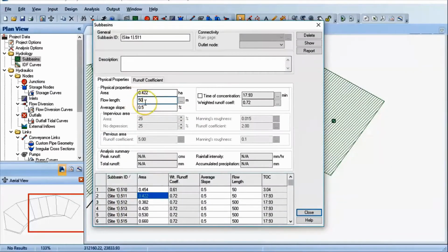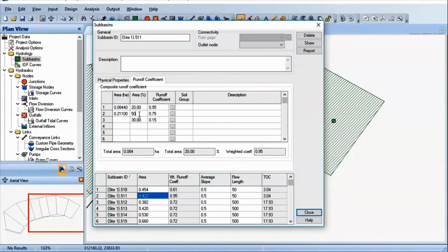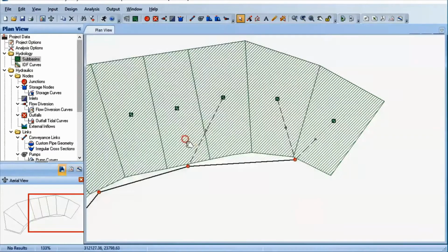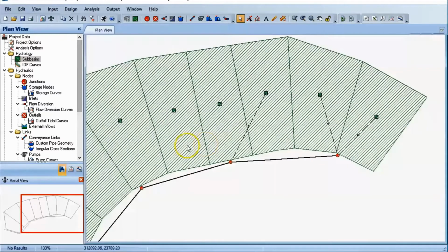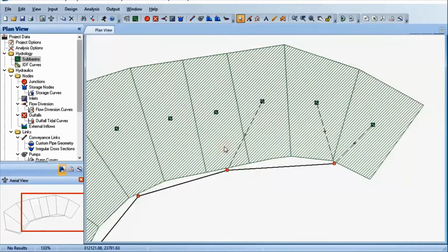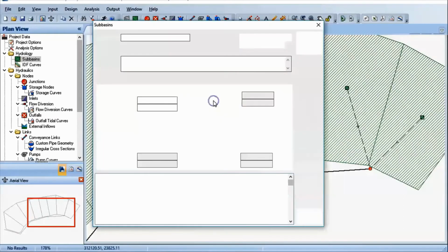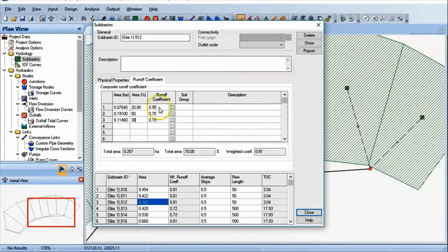Yet again, just to show one more time, if you go to the actual paste, you can see it sometimes does not pick it up. So I need to manually go and change these elements and make sure the inlet selection is correct. You can do a little bit of adjustments afterwards when you've already set this up. But the most critical part is you need to link it to your system. Otherwise, it's not going to calculate any flow into your catchment areas.